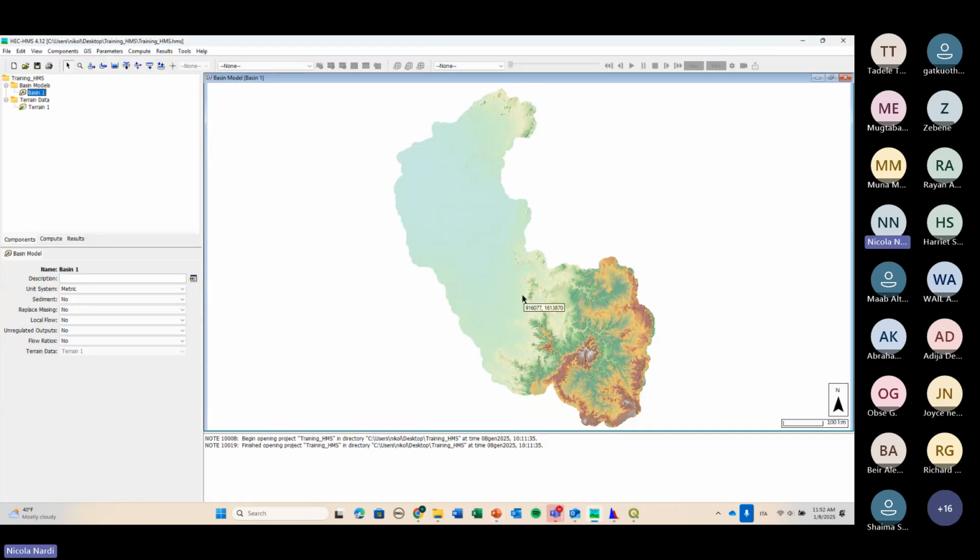And it means that the coordinate reference system that you have to use must also be metric. So the coordinate reference systems that you can use are not so many. You cannot use, for example, WGS84 because it's geographic.